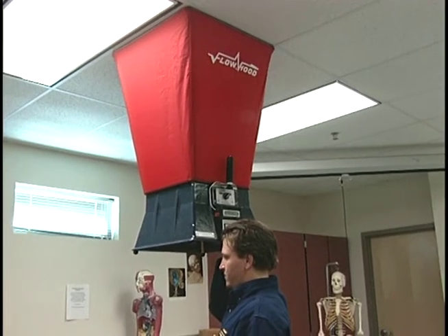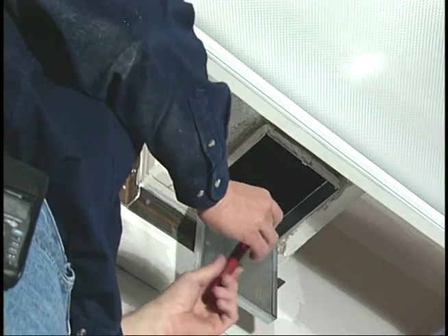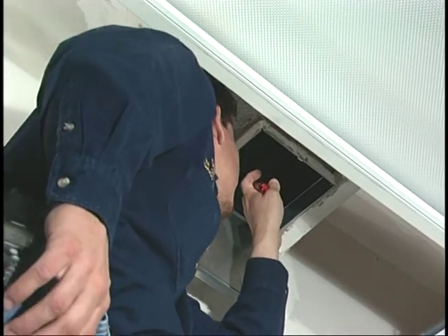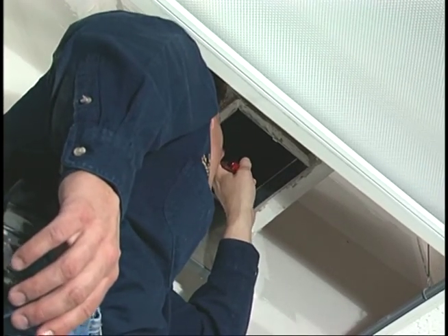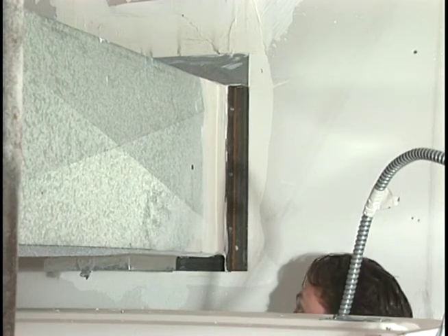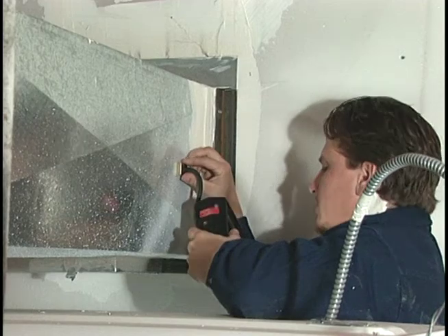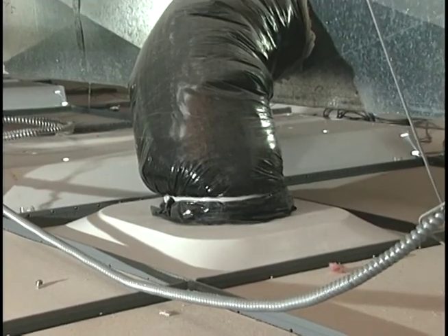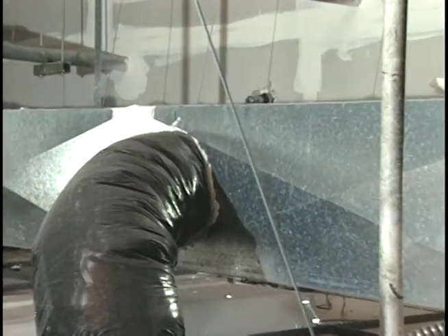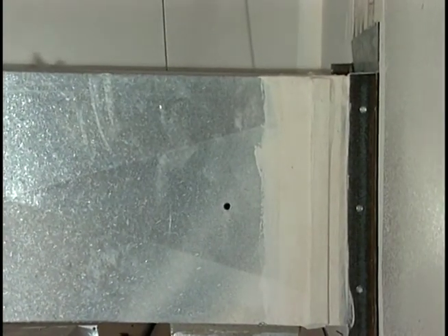If any branch is especially low, the technician will investigate, looking for blockages or excessive friction and dynamic losses in the duct. The cause of the low airflow may be determined by inspection or by taking a static pressure profile of the branch in question. A manometer and static tip or pitot tube is used to take static pressures. When taking a static pressure profile of a branch duct, the technician takes the first reading at the takeoff from the main and progresses along the duct until evidence of a blockage or resistance is found.